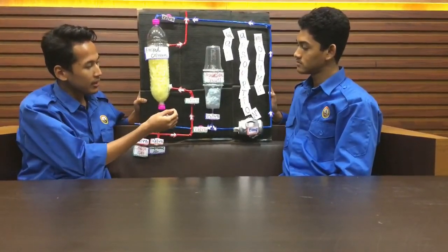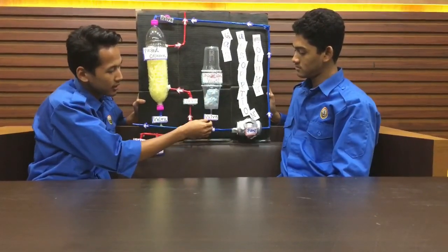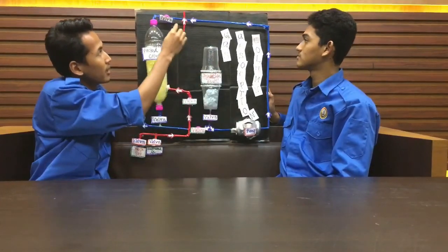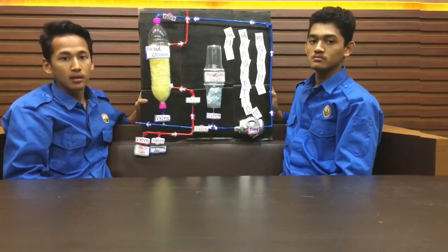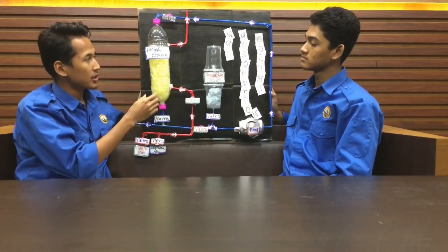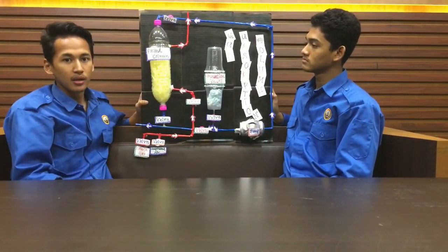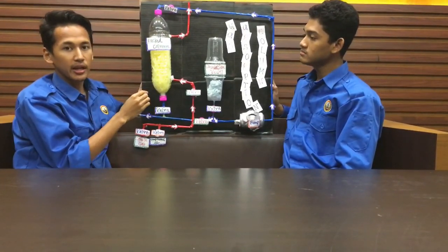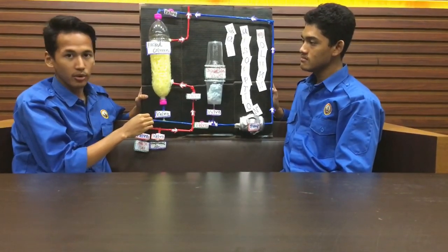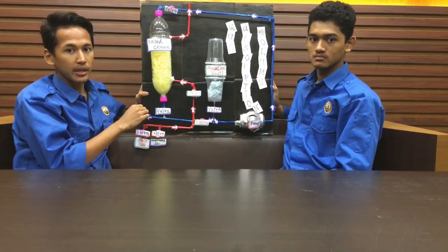Then the liquid is supplied from the circulation vessel into the pump. The valve is open and it will flow into the top of the packed column. Next, for the process in the packed column, the liquid and air will mix in the packed column. The air will rise up while the mixture of liquid and air will go into the bottom of the packed column. Some liquid will be recycled to be fully utilized.